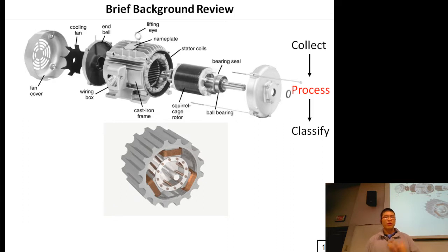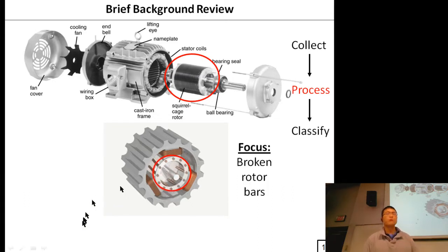Now, for the processing of the data, typically a big area of research is in broken rotor bar fault detection. The rotor bars are within the rotor here, and if there are certain breaks, it would eventually cause the entire motor to fail.